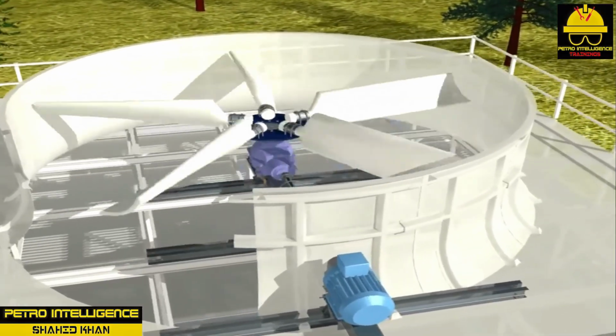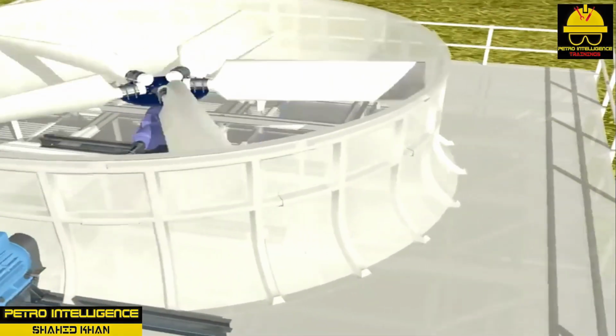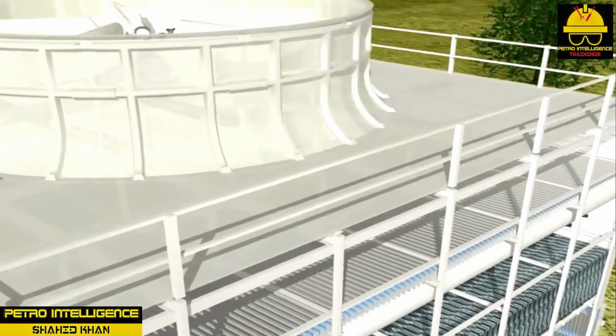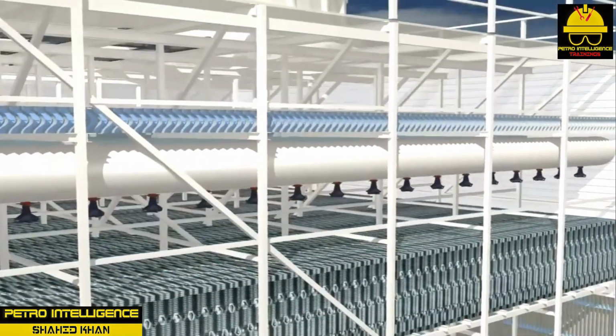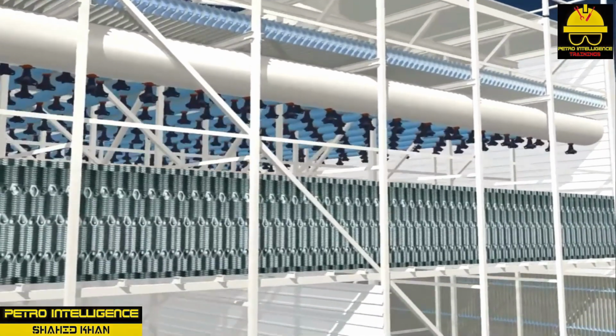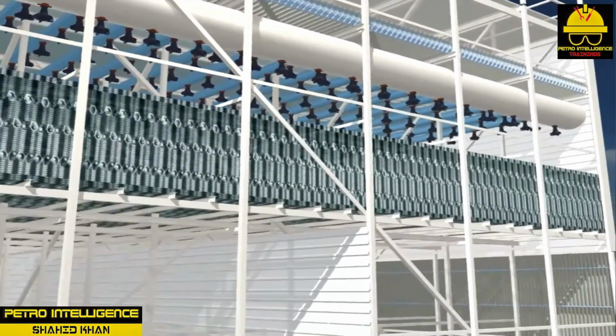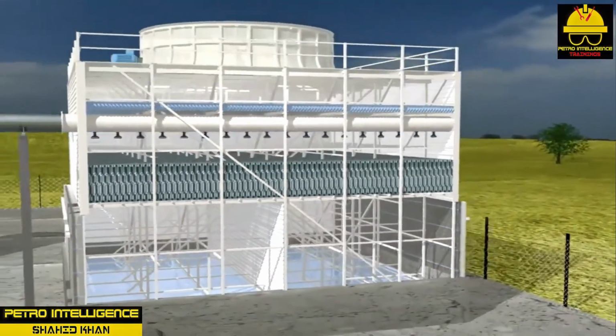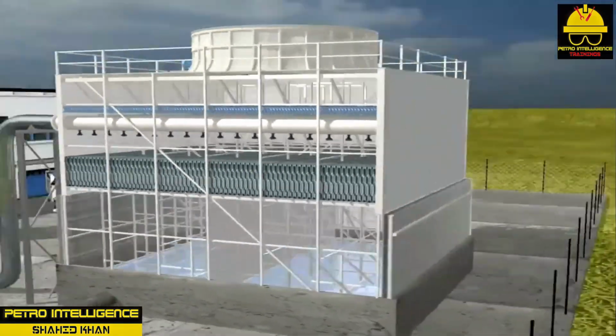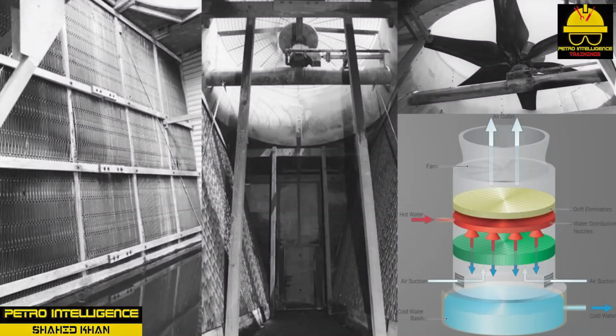The tower fan, located on top of the tower as shown in the pictures, produces a discharge rate strong enough to lift the hot air above the tower, so hot air is not recirculated into the tower. Induced draft towers can circulate airflow horizontally, crossflow, or vertically, counterflow. During crossflow operation, drift eliminators are located in the center of the tower to reduce water loss. Counterflow operations force air vertically across a solid area of fill, and drift eliminators are located above the fill and water distribution headers.